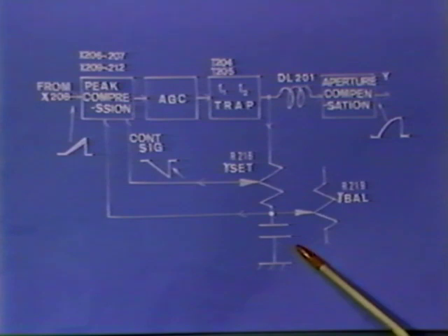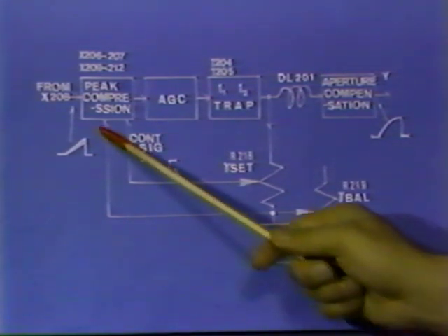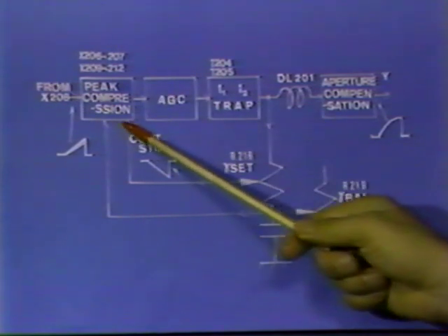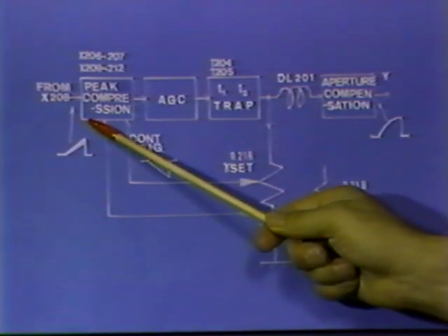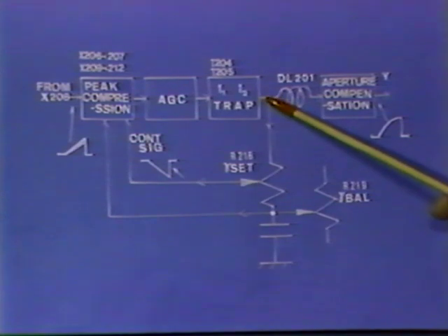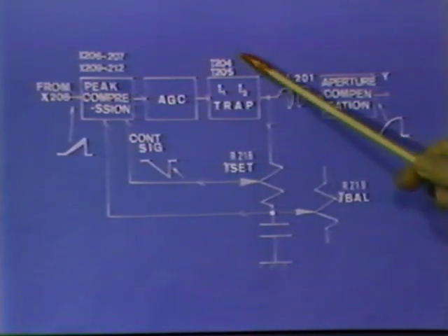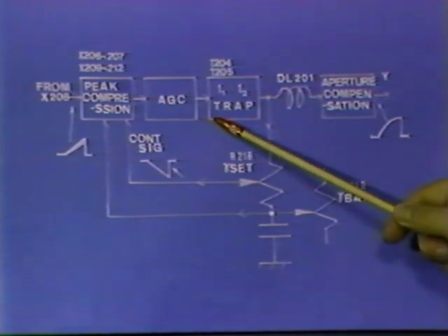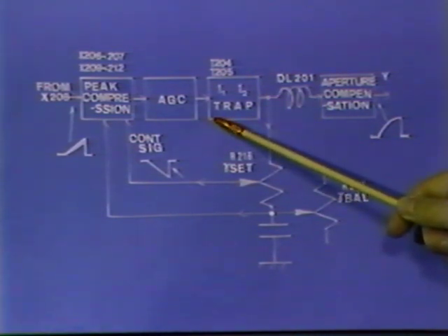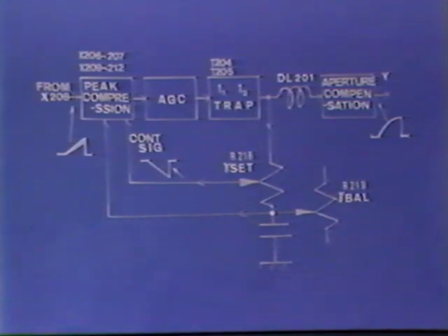The circuit consists of a group of differential amplifiers from X206 through X212. The parallel traps T204 and T205 get rid of the 4.1 MHz fundamental and the 8.2 MHz second higher harmonic from the original color multiplex signal, with the result being only the lower component of it.